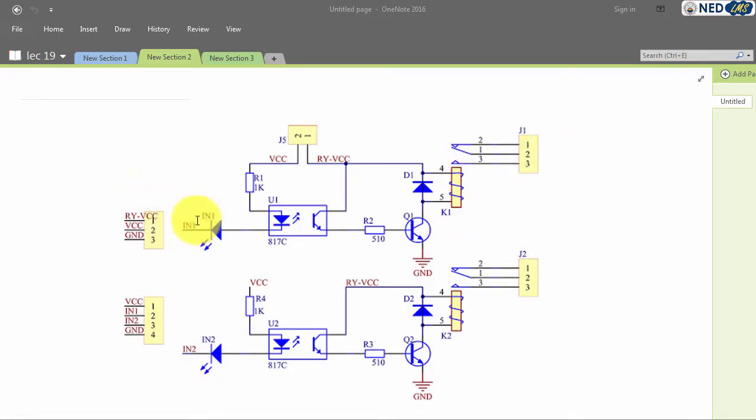Now when the output here is set to high, that means it's 5 volts. This means here is 5 volts, here is 5 volts. In this circuit there is no potential difference. 5 volts here, 5 volts here. There obviously will be no current in this line, and this LED will turn off. This LED will also turn off, because since there is no voltage difference, there will be no current in this wire. This is the visible LED, but the LED inside this optocoupler will turn off.